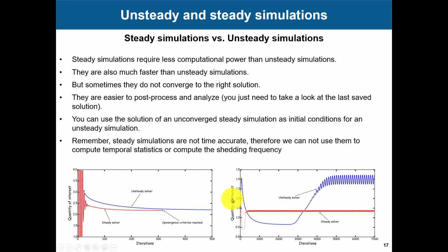But you can also use steady solvers on a steady flow. Here, in the case of the cylinder, Reynolds, I think it was 200, it will give you a solution. But as you are not capturing those features, you get a value that might underpredict or overpredict, who knows? Usually it will underpredict. Also, you can run steady solvers on flows that are in fact unsteady.